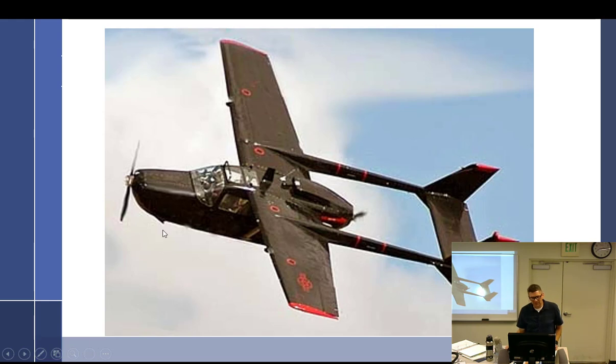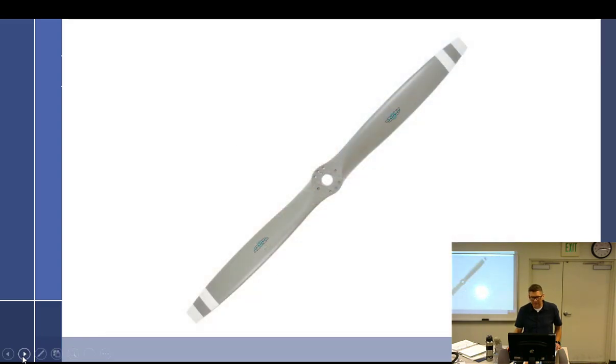The other problem with these is that in a regular twin, you run the throttles simultaneously for takeoff. They came out with, I believe, an AD on this to placard it. If you do this in the Skymaster, you can't see the rear engine and you won't feel the asymmetrical thrust. You will just roll down the runway and take off on single, and you clear the end of the runway and you're not climbing. So they want you to lead with the rear. Bring the rear engine up, get your thrust going, then bring up your second. You should have increased thrust. Interesting. Yeah.